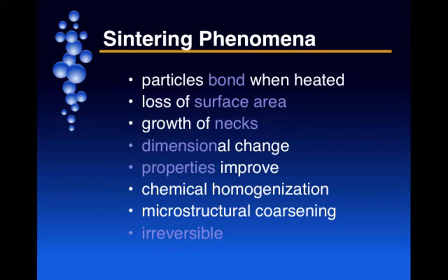Unlike the case in mixing, where if you had a poorly mixed material, you could throw it back into the mixer, or if there are some defective parts after injection molding, for instance, you can regrind the material and reuse that with some of the virgin feedstock, you cannot do that with sintering. After sintering, you're going to be stuck with defective parts. And so understanding the many processing parameters that help you control sintering is important to make sure that you have high yields from the end of the sintering process.